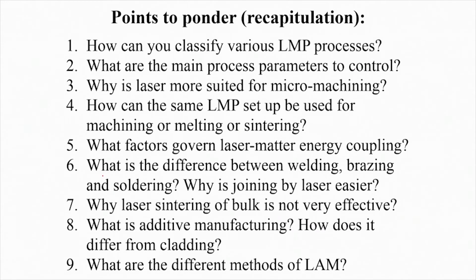Laser sintering is a bit problematic, particularly when you are dealing with dissimilar sizes or dissimilar composition, and that's purely because at a time you are heating only the surfaces of the powder particles and not its entire bulk. But one can actually use laser sintering in combination with application of pressure and then make a denser and a stronger compact or sintered product.